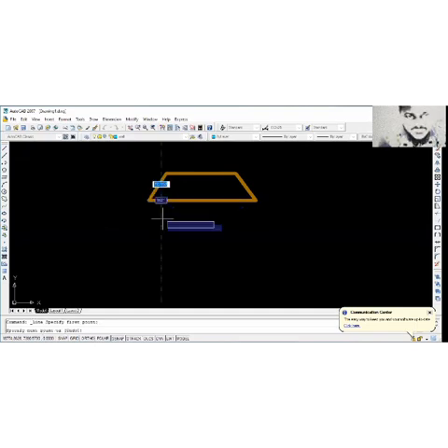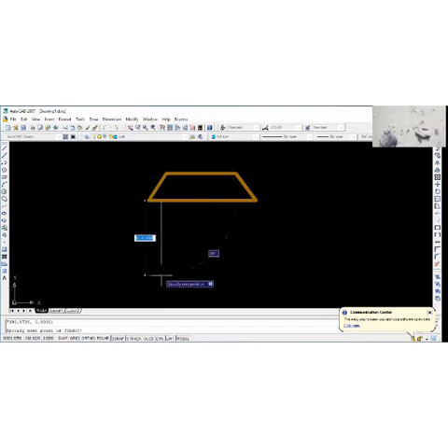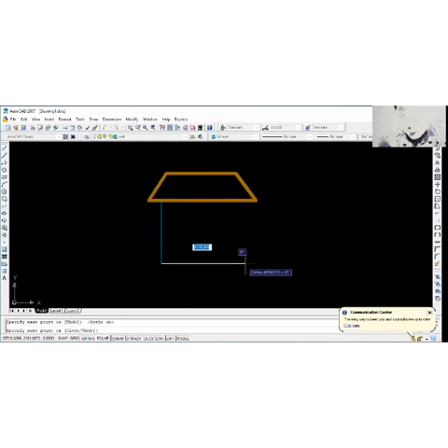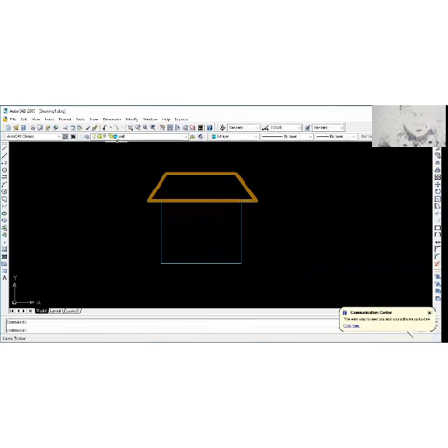I click here, I come down. Okay, let me press my auto command so that it's perpendicular. Good. And then I come here so that it's perfectly horizontal as well. And then I come up and then click on it and then escape. My object snap is also on. So escape. You can see the color of the wall because that's the color I gave to it here. So now that I'm through the wall, then I come back to the layers properties toolbar.